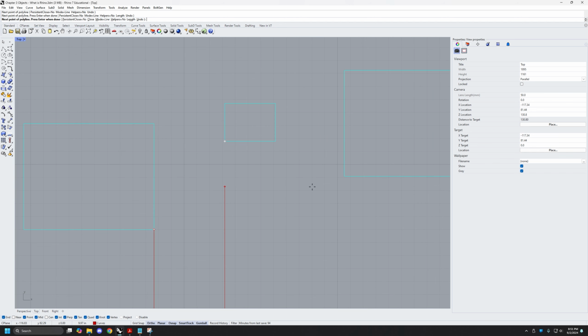Now the next line I want, maybe this wall is in line with this edge of this rectangle. So same thing, right? Hover over to get the gray, bring over my guideline, and now I've got that perpendicular O snap. And then I'm going to click. And then if that is where I'm trying to end up, I can totally do that.